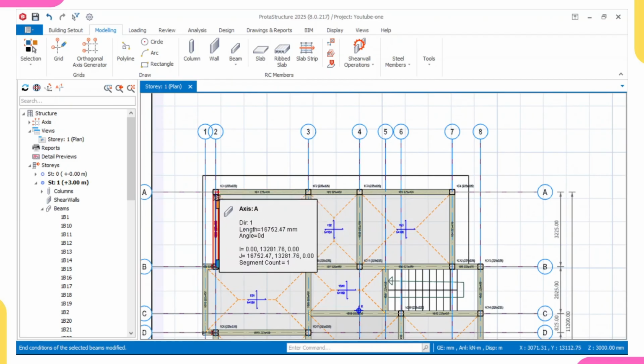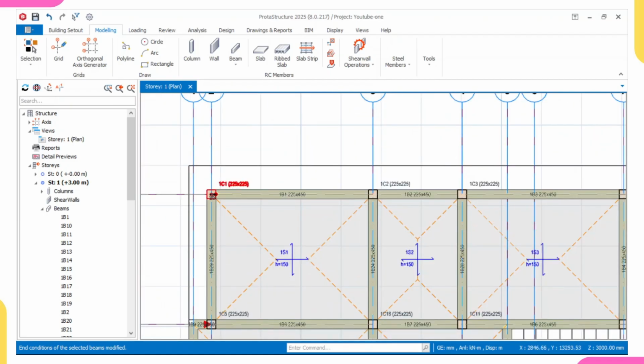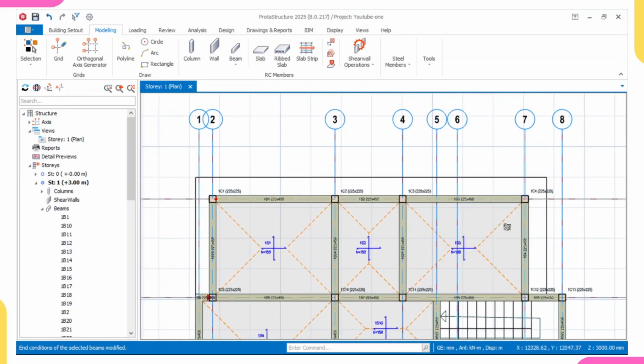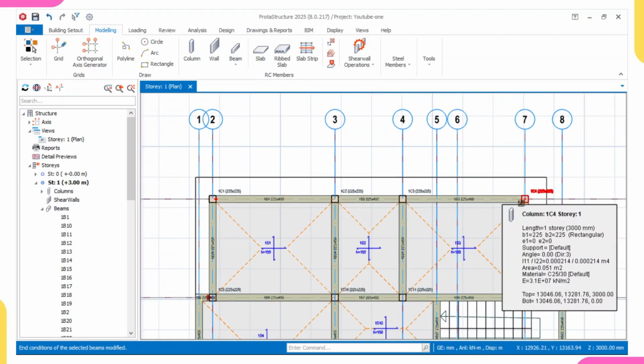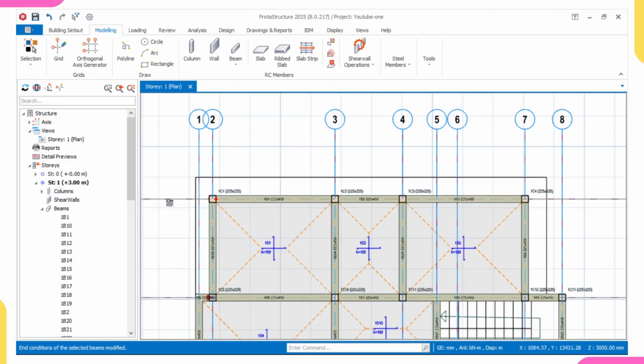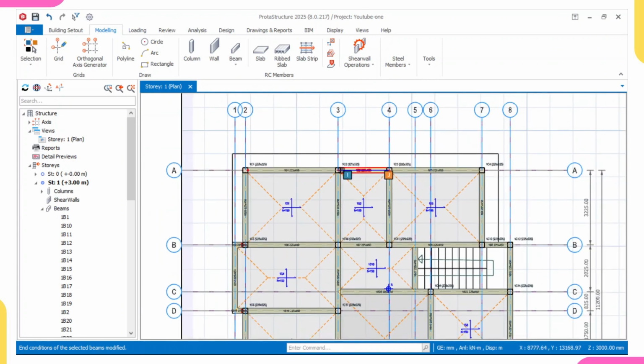So we know that in drawing this beam now, if you want to draw this beam, it will be going like this. It will come here, it will go up, which is hogging moment, it will also come down, it will go up, hogging moment, it will also come down, then it will now come and terminate here. If you can remember your university days when you were drawing bending moment diagrams, your bending moment diagram will go like this: go up, hogging moment, come down, sagging moment, go up, hogging moment, come down, sagging moment, then terminate at 0. I hope and I believe that I've been able to do justice today.